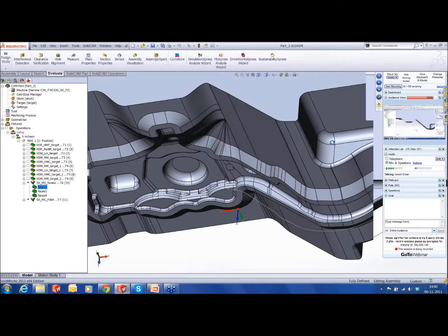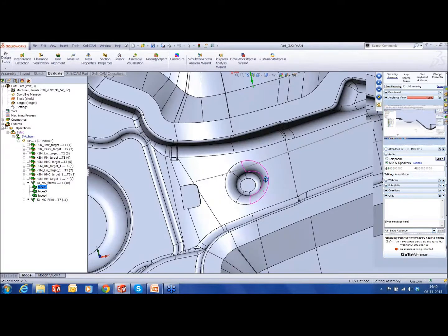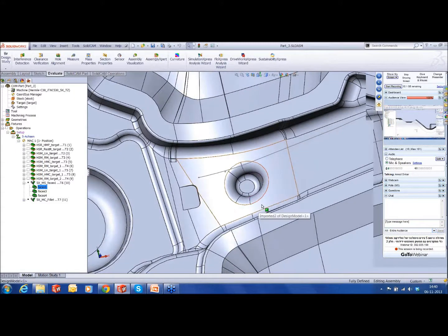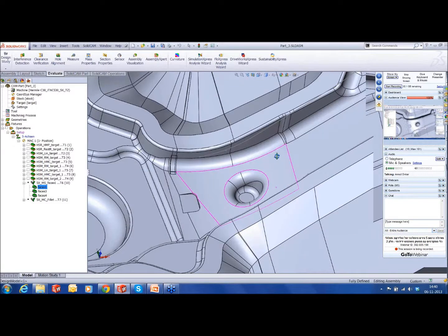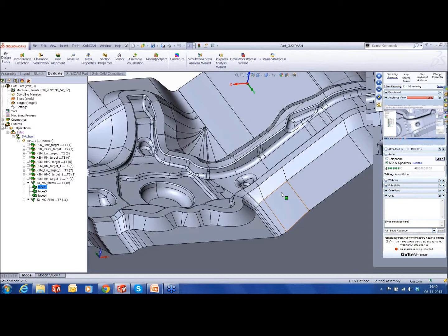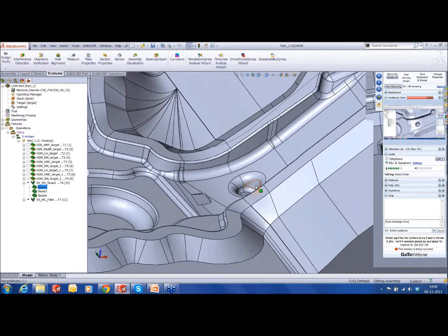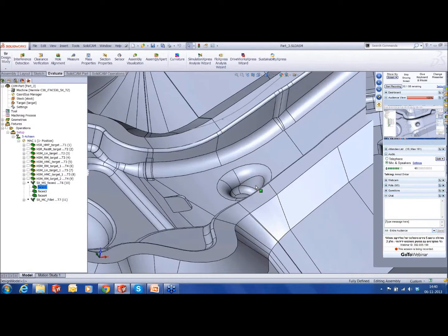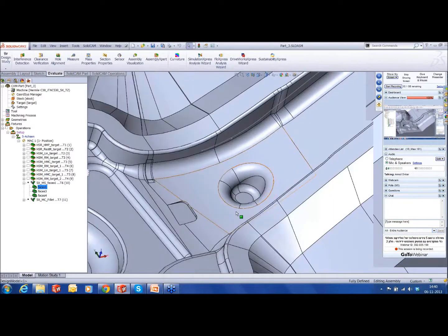Since this area is very small, you're going to need a very short cutter to actually cut this part, or a small diameter cutter to cut this part. So using a small diameter cutter for such a long length is not a wise thing to do, because you're going to get a lot of chatter or vibrations, because it can't sustain that L/D ratio. So for this, we need to go as short as possible, with as short tool as possible in length, also in diameter.